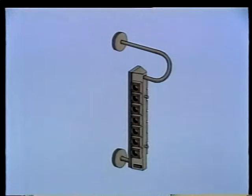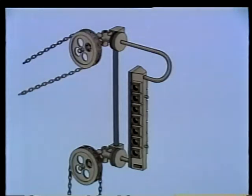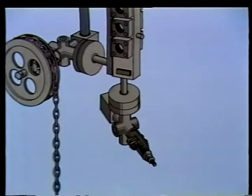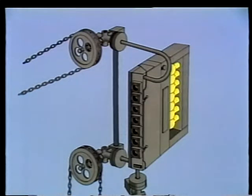There are valves in the upper and lower connections so that the gauge can be isolated for maintenance. In some cases, these valves use chain wheels or some other method to allow operation at a distance. A drain valve may be located at the bottom of the gauge so that the gauge can be drained for maintenance. In this multiple port gauge glass, the fluid level is not visible when it is between ports. To permit easy and accurate reading, a special illuminator is used.